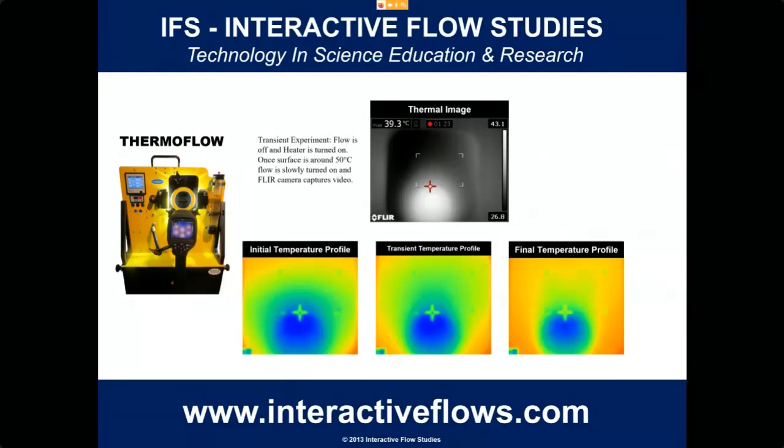Here is an experiment, a transient experiment. Flow is off and the heater is turned on first. Once the surface temperature is around 50 degrees, flow is slowly turned on and the FLIR camera captures the video to see what happens. And later on, we also perform a PIV analysis on this too. So as you can see, flow is slowly turned on.